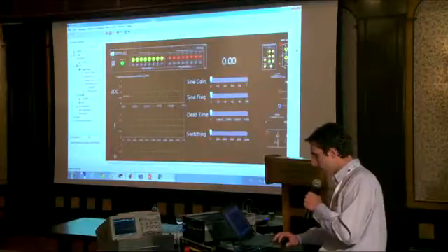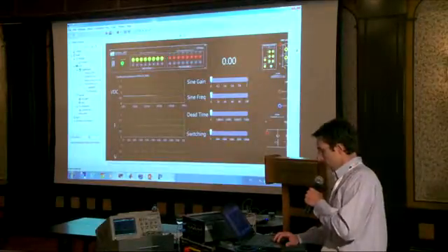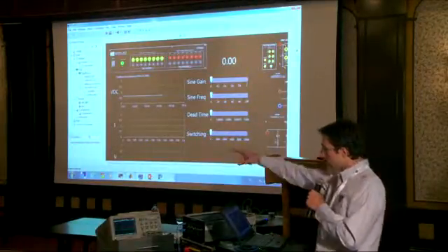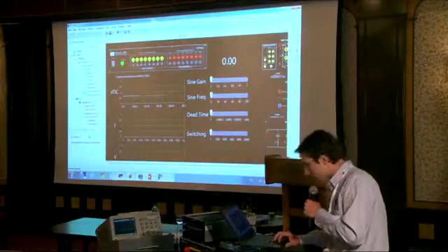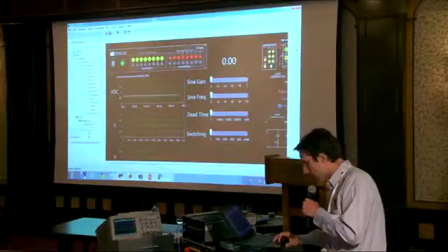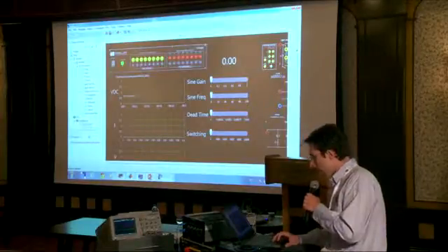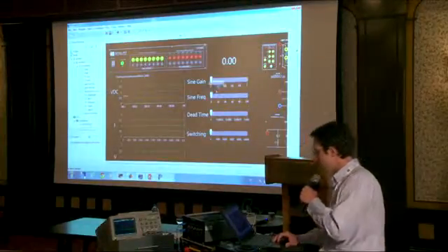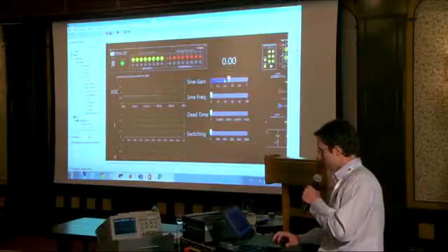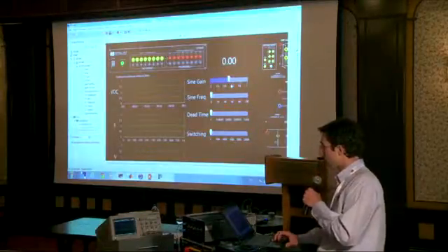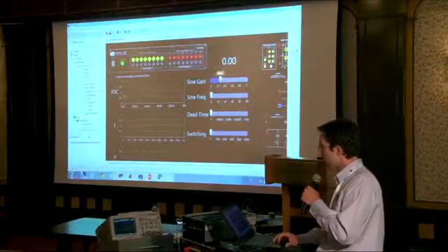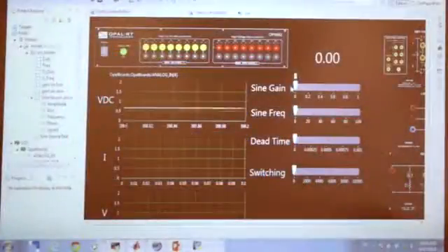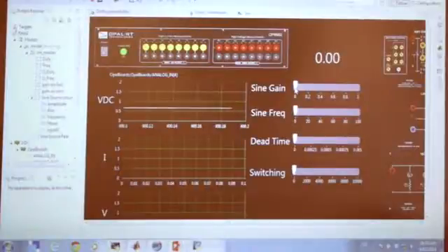So what can we do next? We can say, okay, let's look at the model, because we know that the sine wave that we generate here is coming from the Simulink model that is running in real time. So this is the sine source, the slow sine wave that we have here. And we can say, okay, let's modify the amplitude of this guy. So we drag this to a control. So now we have a 50%, 0.5 duty cycle. So if I go to 0, since I'm dragging, you see the result directly on the scopes.